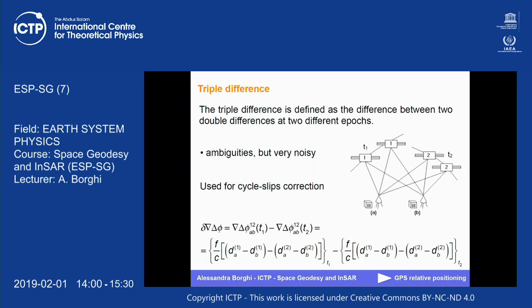So if you process data step by step, you can see all this process from the raw data, just the observations from one station, and how we are going to build this type of processing. Computing baselines, connecting points with baselines, and computing differences.